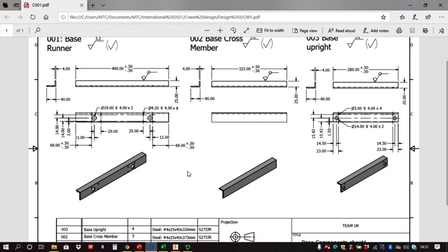Okay, so there's a few extras on this particular drawing. We've got the dimensions. I've got a specific tolerance. On each one of these drawings there is a specific tolerance. There is the machine finish that's required. There is a symbol that tells me that all around no finish is allowed, so no surface removals allowed at all.